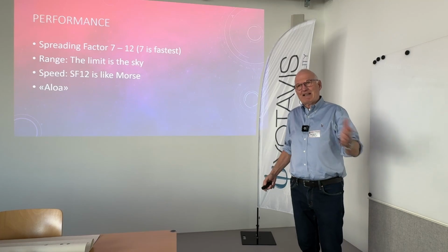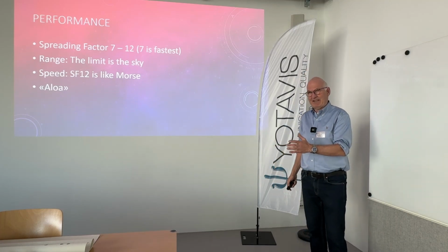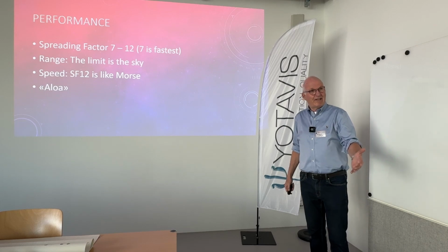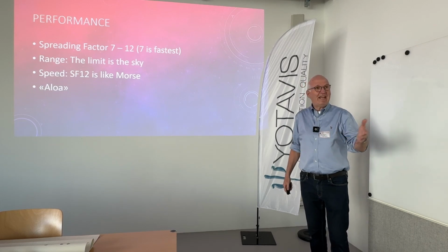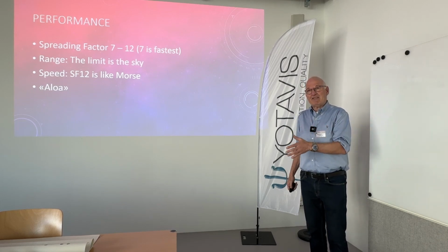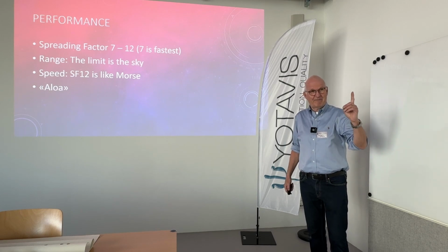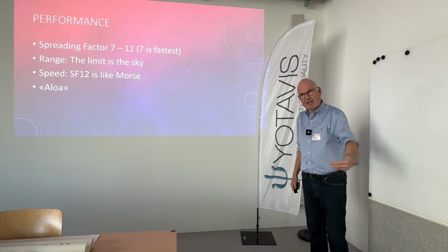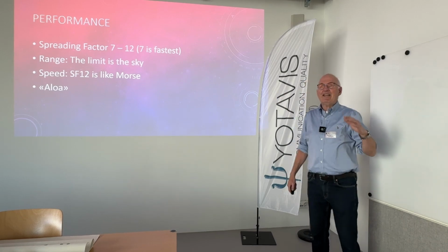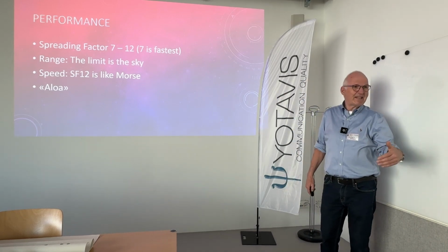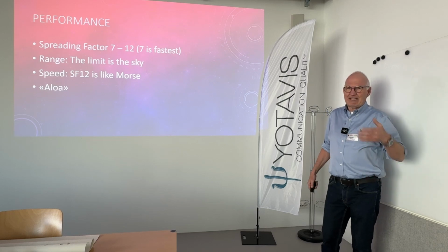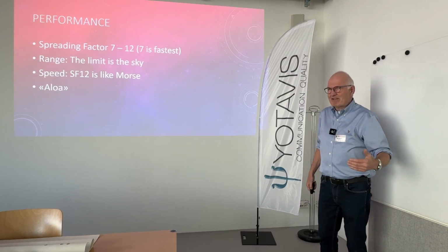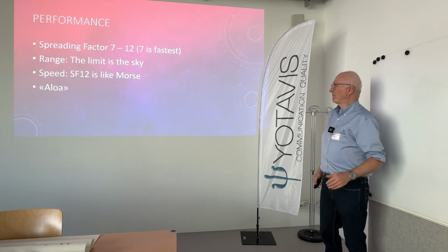There is no feedback channel in LoRaWAN. Very important. You can send 6, 7, 8 or a little bit more messages every day. So it's really not made for a back channel. It's the up channel. It's sensors. And if you do not get the temperature this time, you get it next time. So that is the principle. So I would not do financial transactions with it, probably.